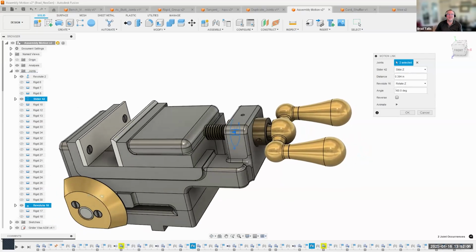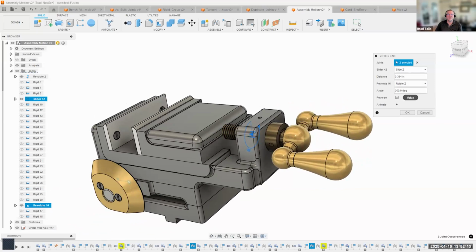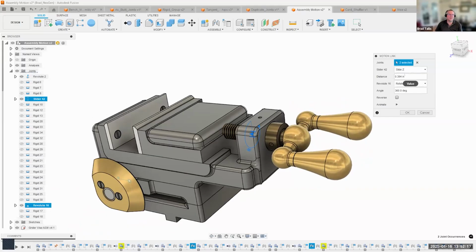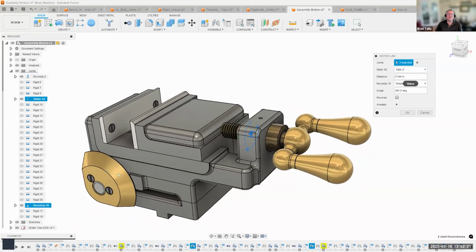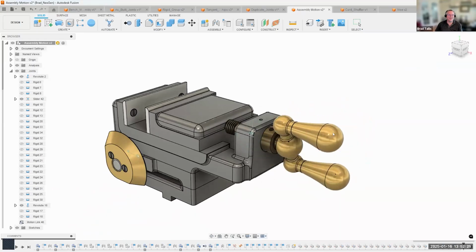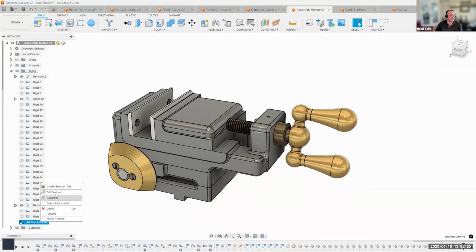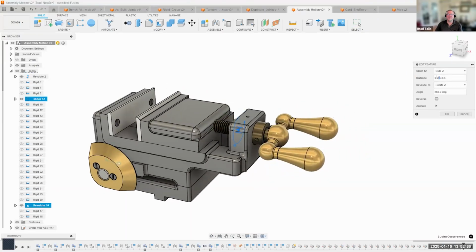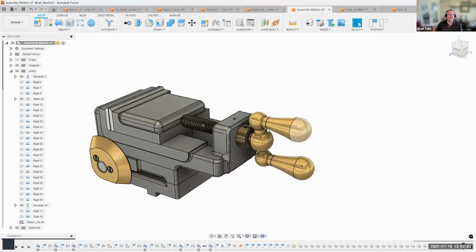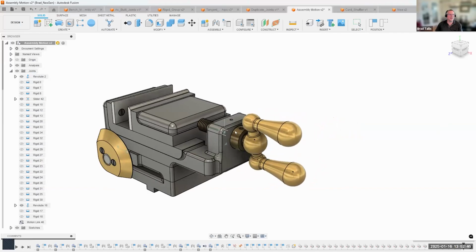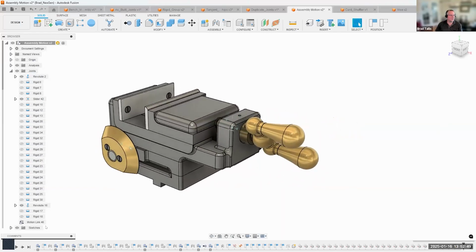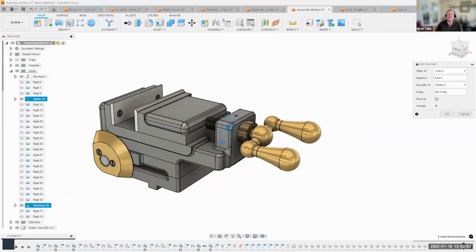So what this is basically saying is for every rotation, for every 360 degrees that this rotates, the slider is going to move 0.394 inches. So for example, if I were to put a 0 in front of that and said, okay, I'm going to have to crank this handle quite a few times for that to move. So it's a very fine measurement, for example. If I were to change that to 0.94, I barely have to rotate the handle and it's going to move quite a bit, right? So you have the ability to control, for every revolution, what's the distance that it needs to move.